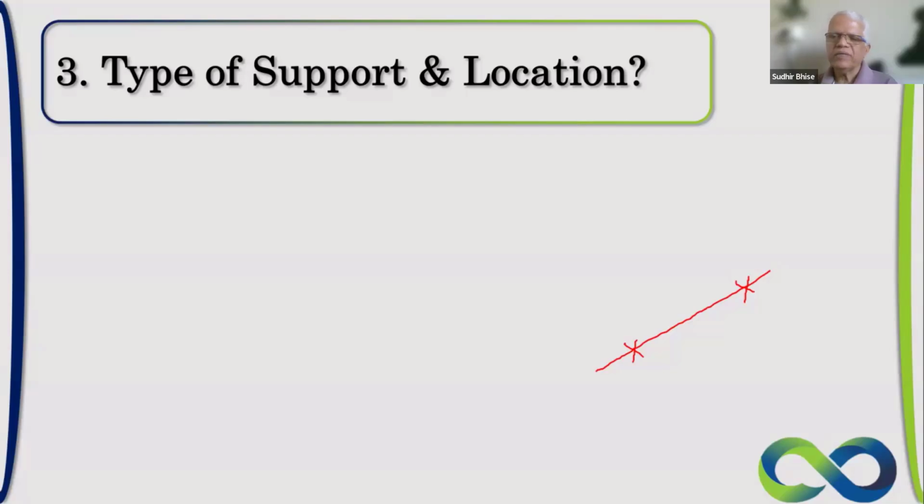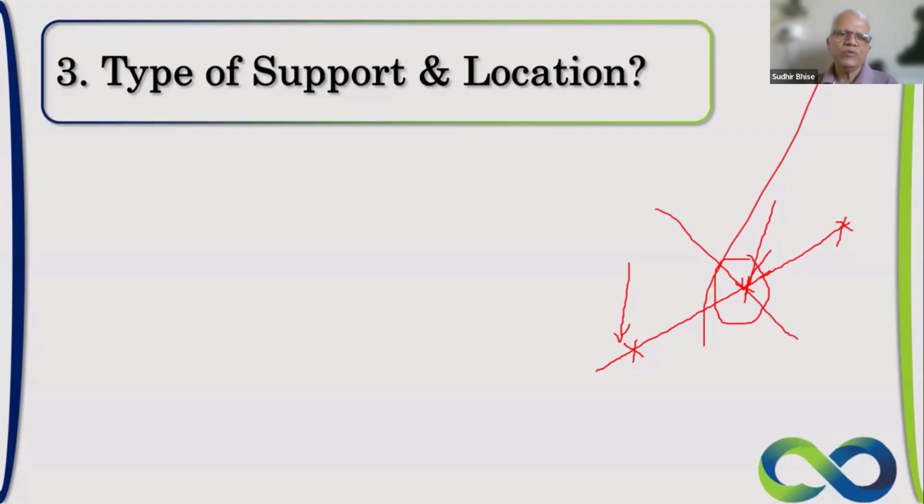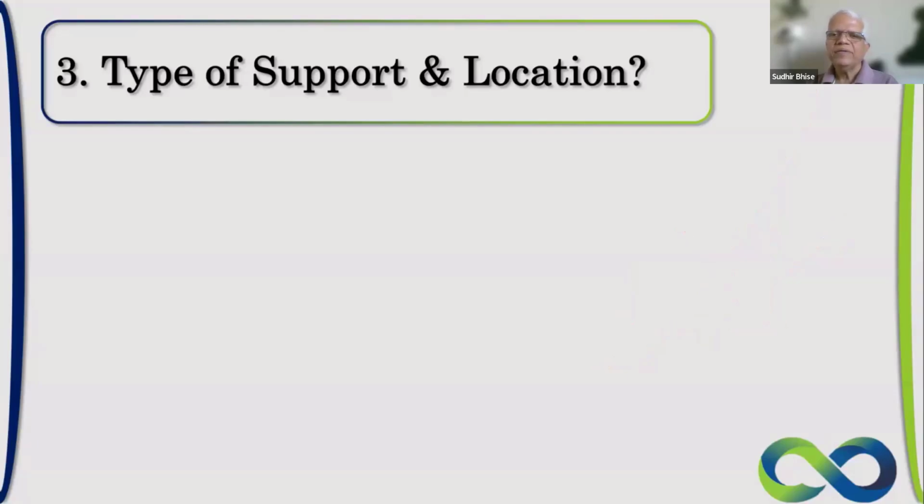Now, whether a guide is to be used at this point, or a fixed point is to be used at this point, or whether this point should be used at all or not. I don't want to use this, and I will use directly the next point. This I'm not going to use. The location which is shown here is not going to be used. I'm going to use only the next point. So this is all decided by the person who is doing the analysis, and it is the responsibility of the stress person to do this.